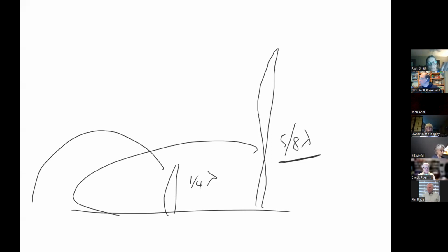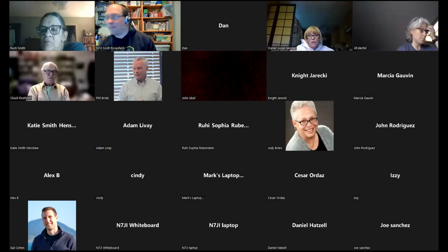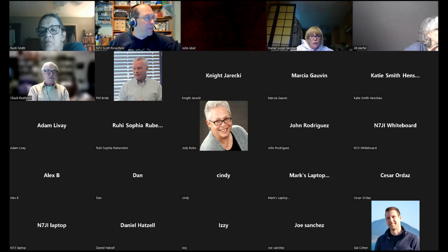And since most of the people you're trying to talk to are along the ground, a 5/8 wave antenna is a better antenna, except that this is 19 inches long and this one is 45 inches long. So if you have a sport utility vehicle and you park a car in a garage, which one do you pick? The 19. So could someone make a rubber duck out of that? The problem is if it's a mobile vehicle, as soon as you start moving, the antenna is going to bend, in which case the pattern is going to be all messed up anyway.